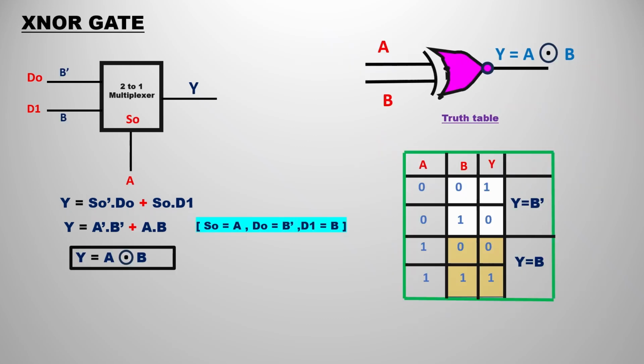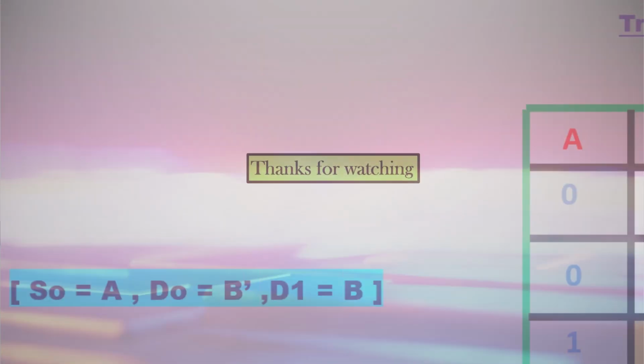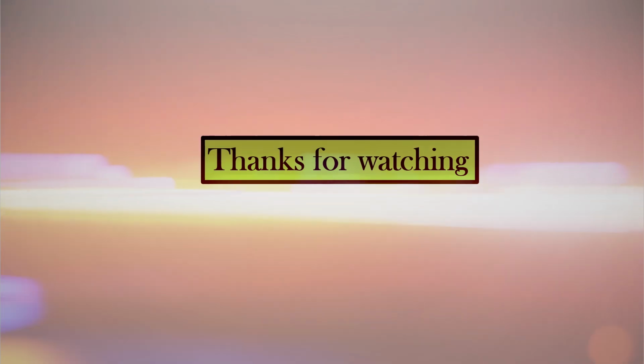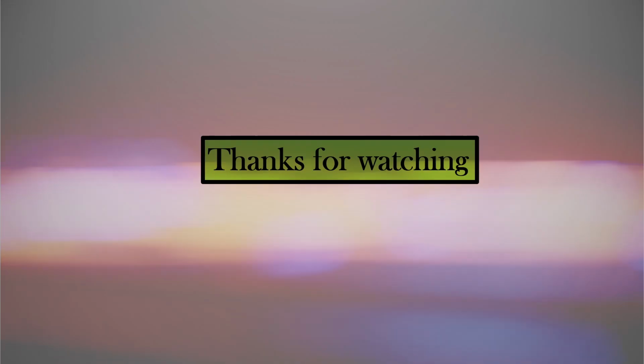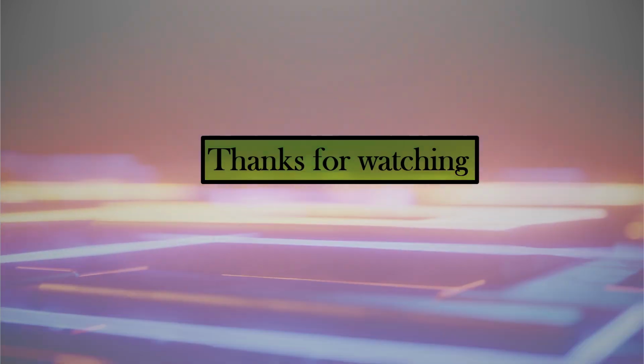Again follow the same procedure. You get Y equals B bar, and again Y equals B. Put these into the output expression of the 2x1 multiplexer, and you get Y equals A XNOR B, that is A bar B bar plus A B. This is not over yet. We can implement any logic circuit that we want. We can implement half adder, full adder, half subtractor, full subtractor, any of these.